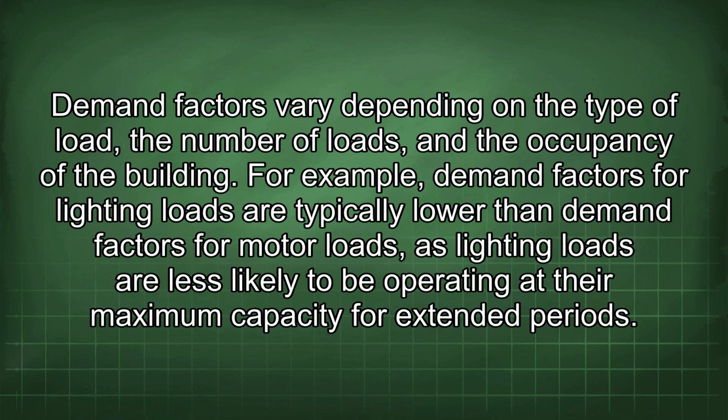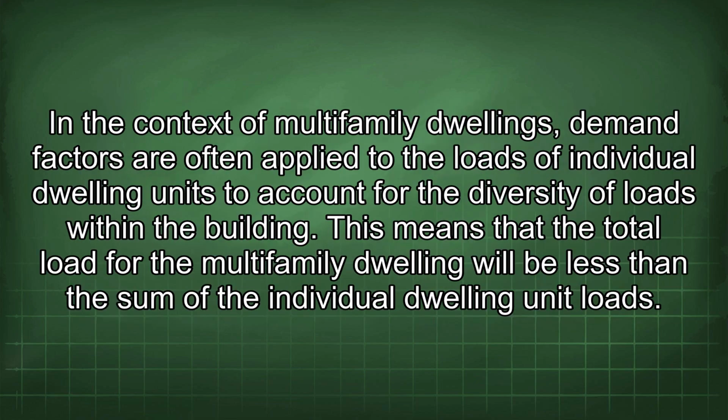For example, demand factors for lighting loads are typically lower than demand factors for motor loads, as lighting loads are less likely to be operating at their maximum capacity for extended periods. In the context of multifamily dwellings, demand factors are often applied to the loads of individual dwelling units to account for the diversity of loads within the building.